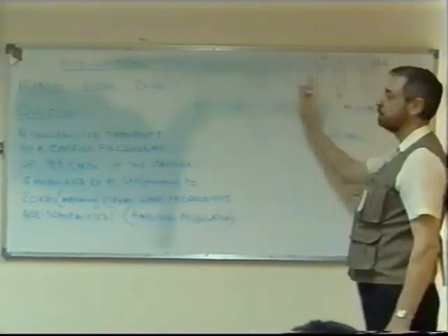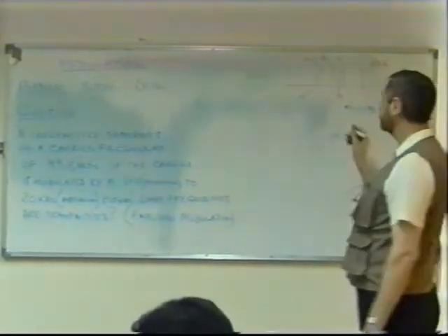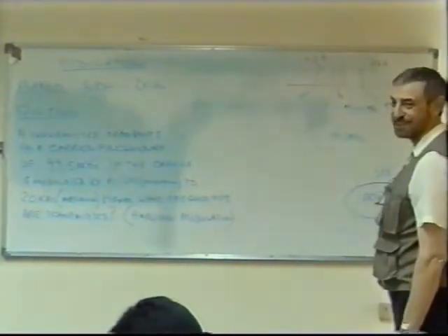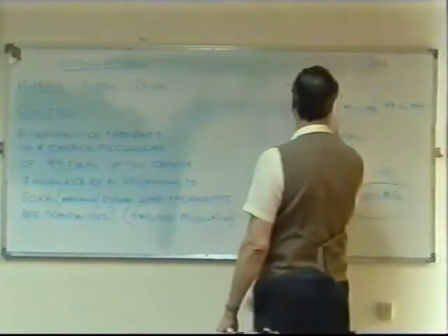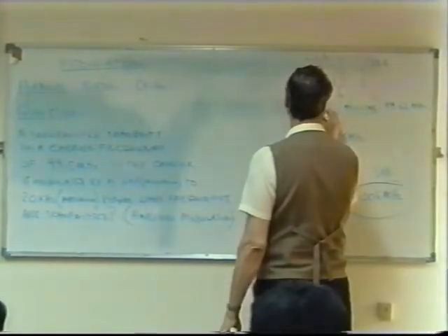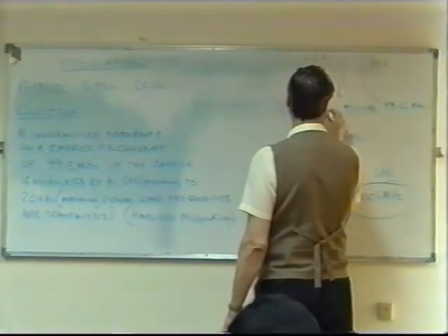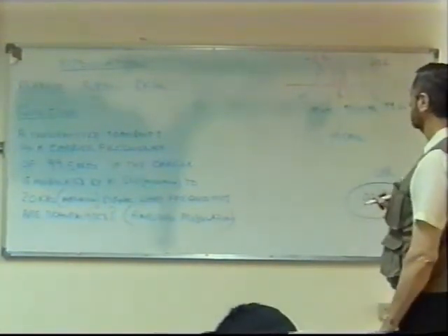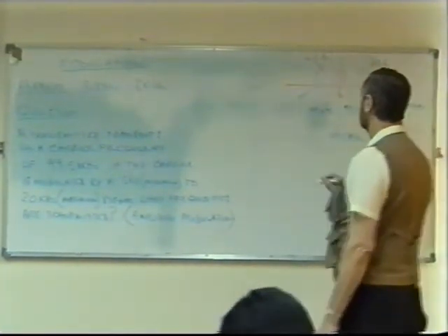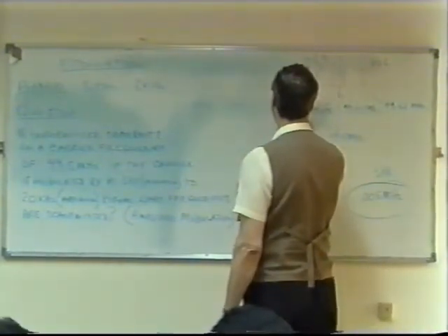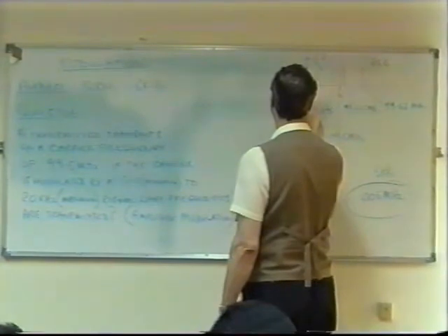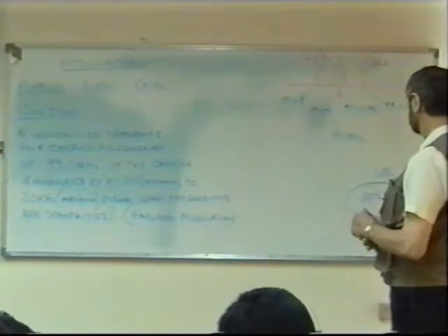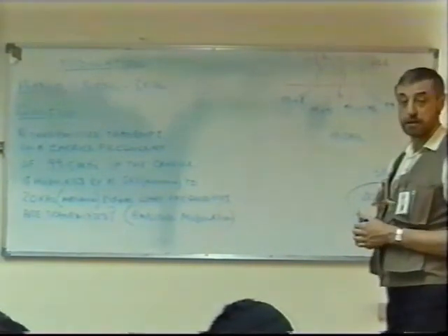And now if we look at the lower side band of frequencies that are transmitted, 99.5, here it's 99.5 minus 0.005, isn't it? 99.495. Isn't that right? Megahertz. They're all in megahertz. That's right. And 99.48. Yes. That's exactly right. Those are the frequencies that will be transmitted.